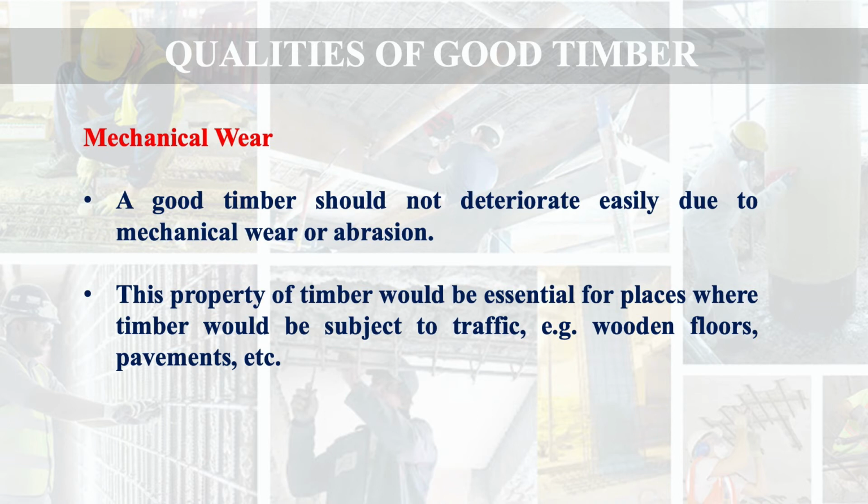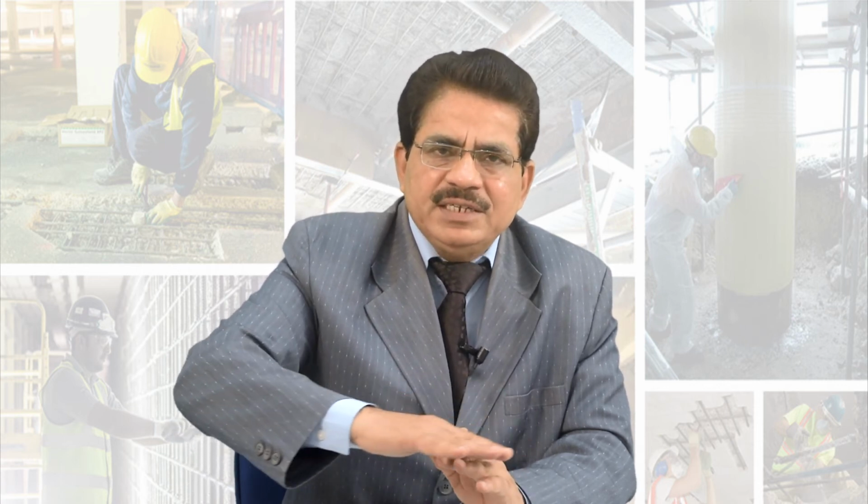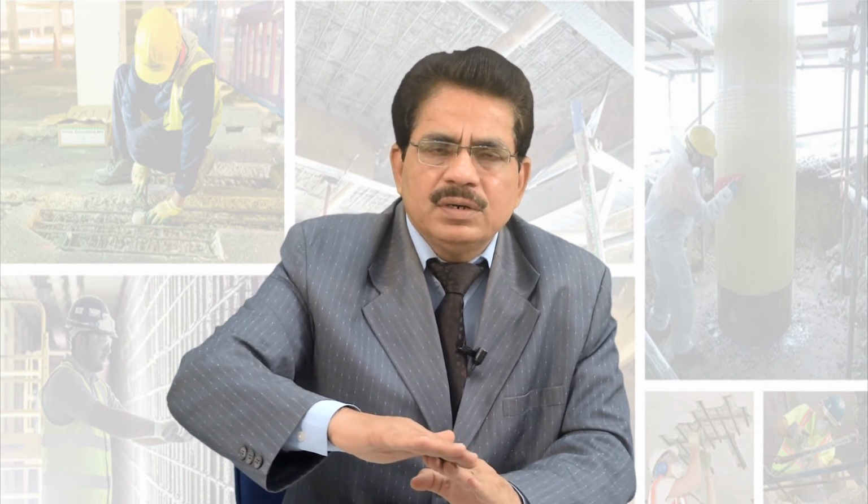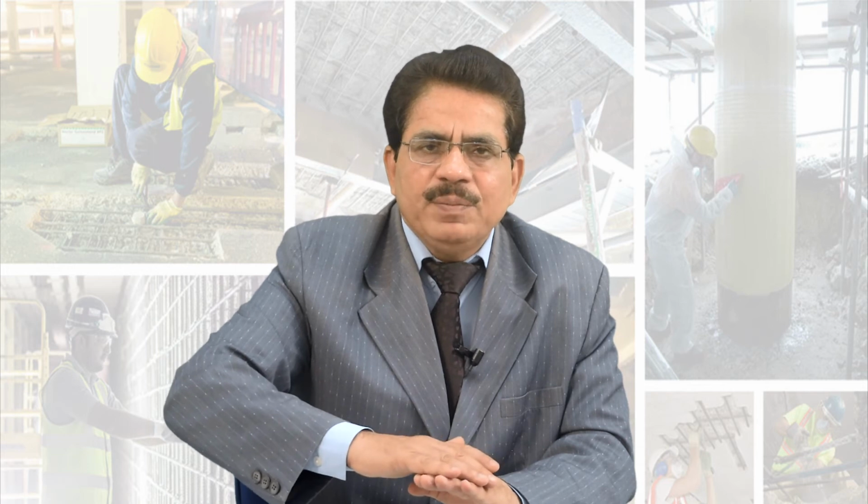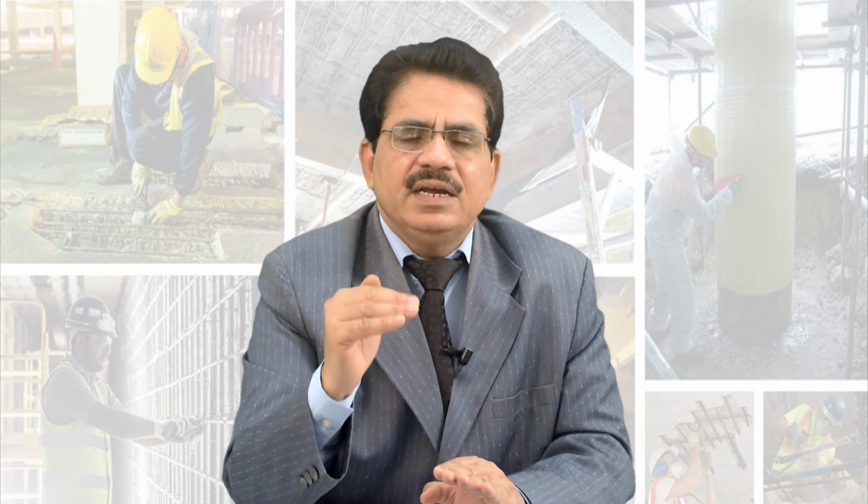This property of timber would be essential for places where timber would be subject to traffic, that is wooden floors, pavements, etc. Due to the motion of the traffic, there will be abrasive action, and if the timber is not capable of resisting this abrasion, then there will be wear and tear to the timber, and ultimately there will be a failure of that surface. The timber should have enough resistance to the mechanical wear.